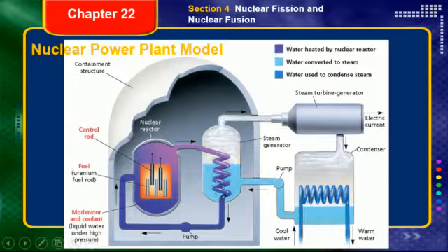This water, okay, this high-pressure water, this coolant is going to absorb the heat. It's going to expand because when things are heated, they expand, they become less dense. And so they're going to rise up. They're going to move through this pipe right here into this area where we simply have water, regular old water, that's going to be exposed to this high temperature liquid, depositing that heat into the water, causing that water to evaporate. Okay, we're creating steam here.